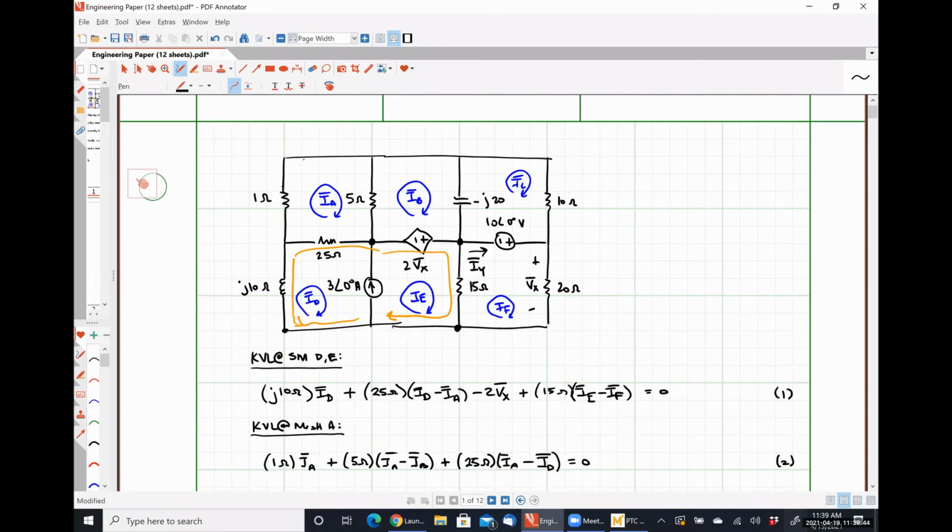So here's another place where things can go awry. So this is a voltage controlled voltage source, right? Which means that coefficient of 2 should have units of volts per volt. So that should work as it is right now in MathCAD. But if this were a current controlled voltage source, I would get a unit error because this 2 would implicitly have units of volts per amp that would not be specified. So it would mix things up. So the 2 I'm putting in there in my current MathCAD sheet is okay. So that's not the error, but that's a very common place you could get an error.